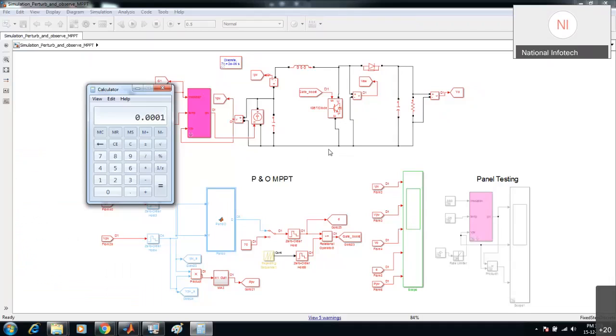10 kilos. Okay, so this is 100 microsecond. Your maximum controller should work at a minimum of 100 microseconds. If it is working at 1 millisecond, then it won't be working properly. Your carrier won't be generating properly.